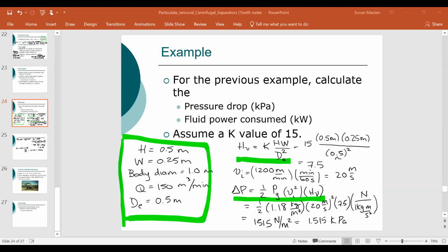Basically, the force of collection acts on the particles, not on the gas carrying those particles. The goal is to change the surface charge on the particles so that they migrate to a collection wall. These devices have very high efficiencies.